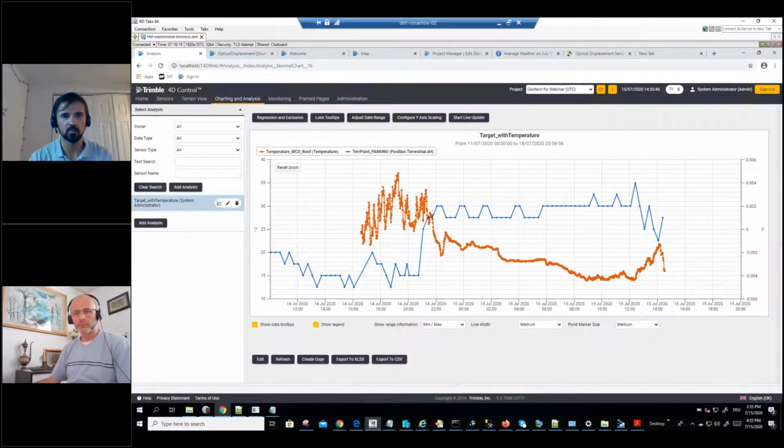If I had a project where I had multiple geotechnical sensors, but also geodetic, like GNSS, total station, and maybe level observations, I can combine all of that in one T4D project and then create these views like you're showing, where I have multiple sets of data in one view, whether it's GNSS or a temperature sensor, whatever it might be. Is that correct? Right. Yeah.